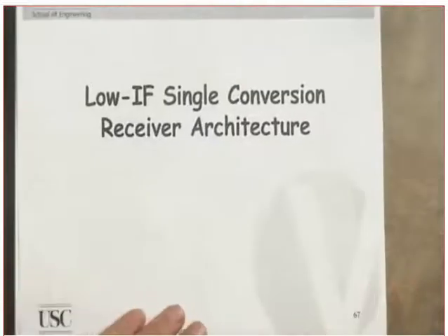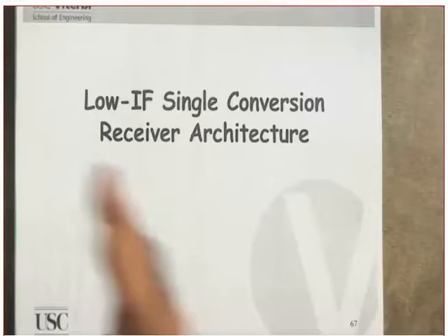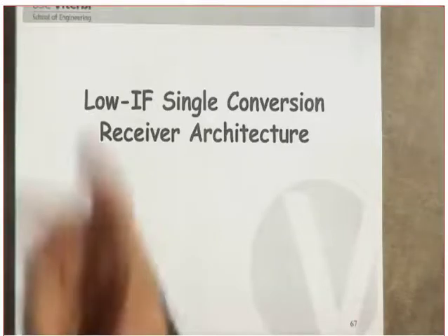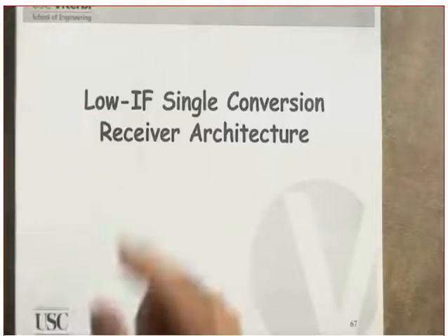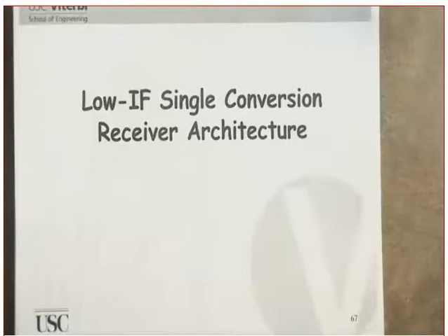Low IF. What does that mean? You are not going to go directly to DC, but you are going to down convert your RF signal way down, to a point which is not zero IF, but a low IF. That low IF is roughly, as I will show in just a second, let me show it to you so that you understand what I'm talking about.